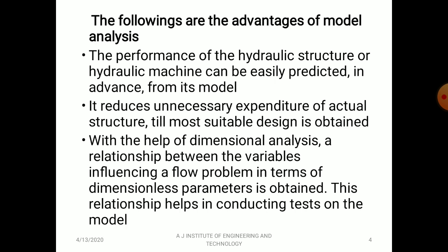Next, the following are the advantages of model analysis. The first point: the performance of hydraulic structures, that is dams or spillways, or hydraulic machines, turbines or pumps, can be easily predicted in advance from the model. So by constructing or manufacturing the model, you can understand the performance of the hydraulic structure or hydraulic machine. It reduces unnecessary expenditure on the actual structure till the most suitable design is obtained. By constructing the model, you can reduce the cost involved in the actual structure, and you can modify the design until you get a suitable design.